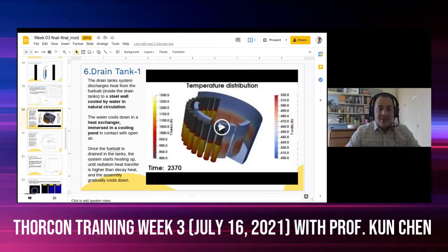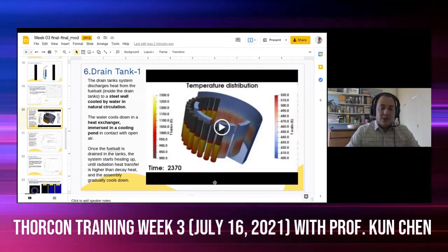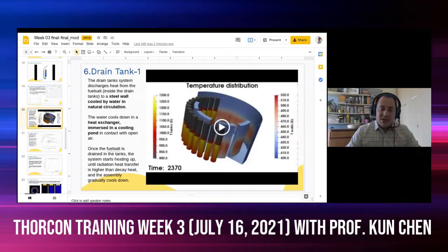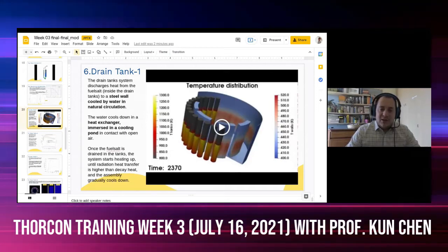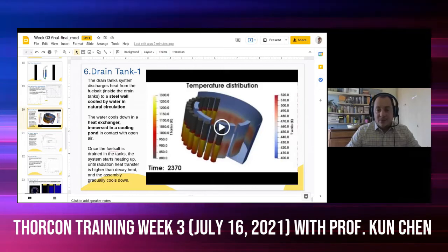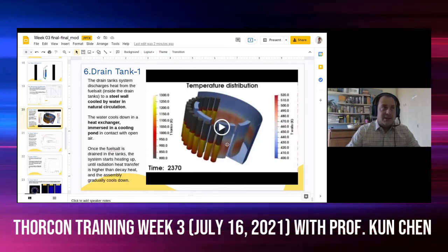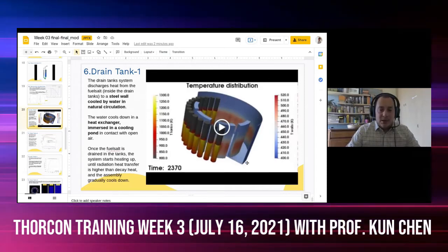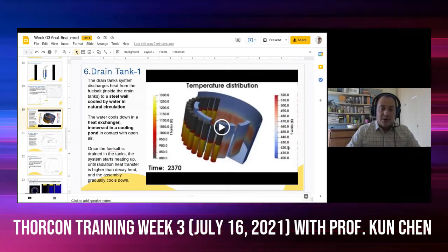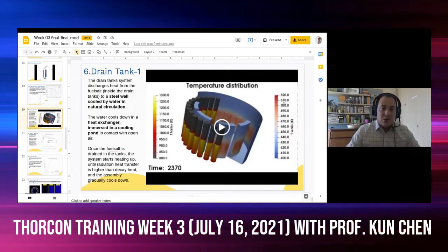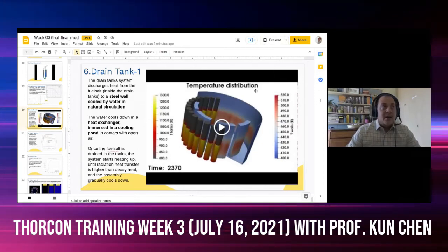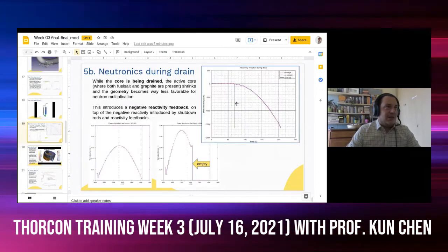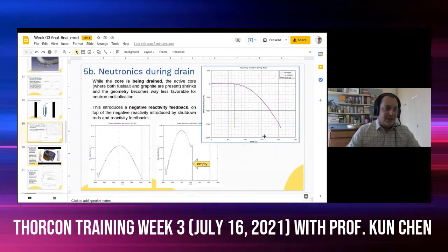Then the passive evacuation of heat from the drain tank to the cold wall due to radiative transfer, a phenomenon whose surface heat transfer rate increases very steeply when the temperature rises, and then the heat is ultimately evacuated due to the natural circulation of water and water-steam mixture in the cold wall to the silo up to the pond. That's the main purpose of the draining. I apologize if I misled you discussing the negative reactivity during the drain.